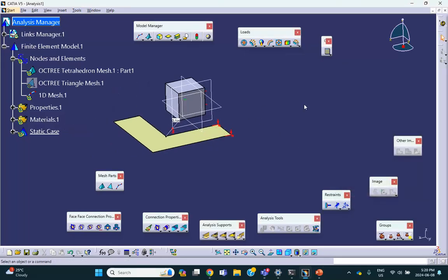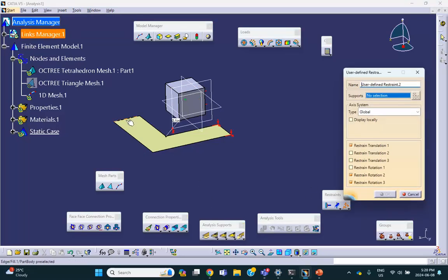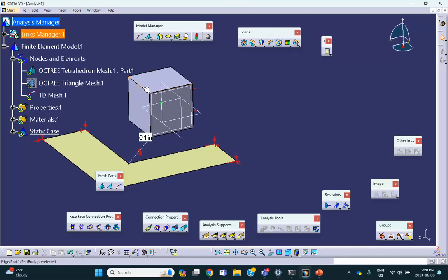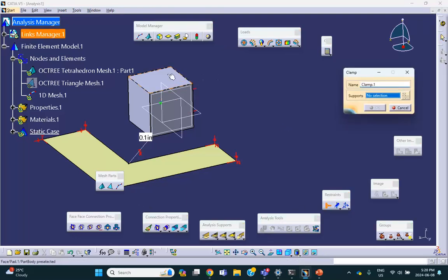The other side, meaning that edge lies in the XZ plane and therefore no displacement in Y, rotations opposite. Good. Some stuff are clamped up here, this and that are clamped. You're told is clamped. So clamp this edge and that edge. Very good.